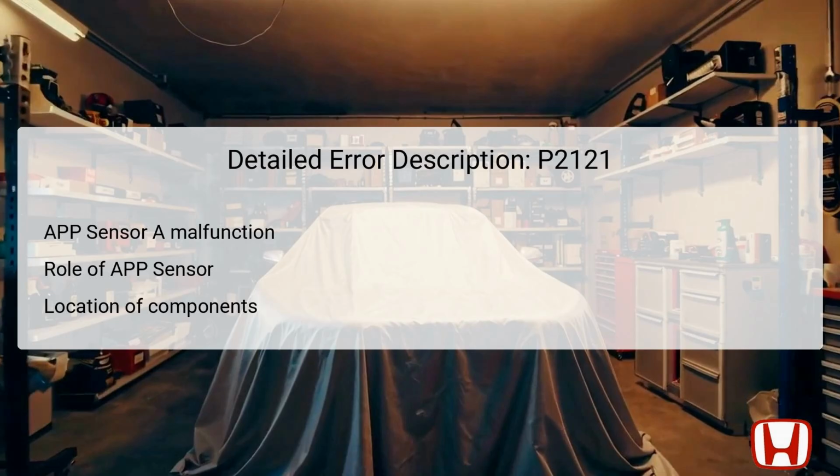The APP sensor is situated near the accelerator pedal assembly in the vehicle's footwell. If the signal sent to the PCM is either too low or too high, the vehicle's performance can be compromised. Therefore, understanding the relationship between the accelerator pedal position and engine management becomes crucial in diagnosing this DTC.